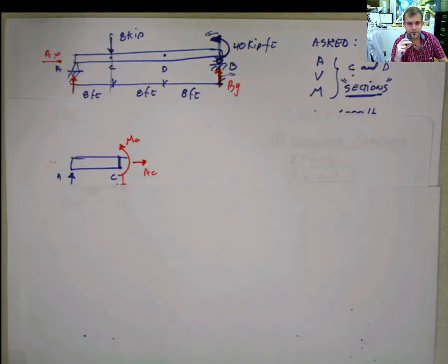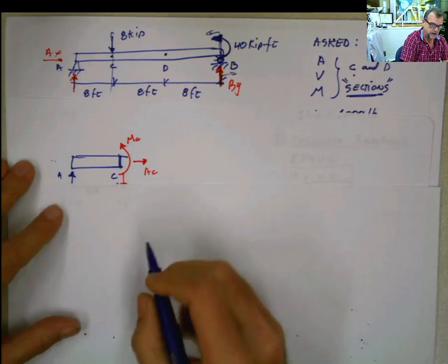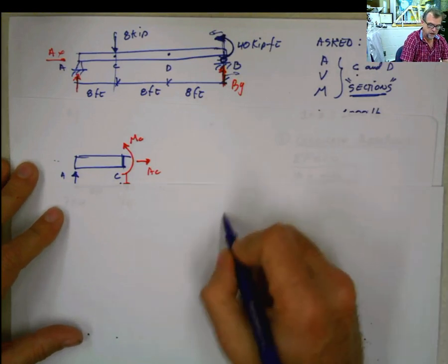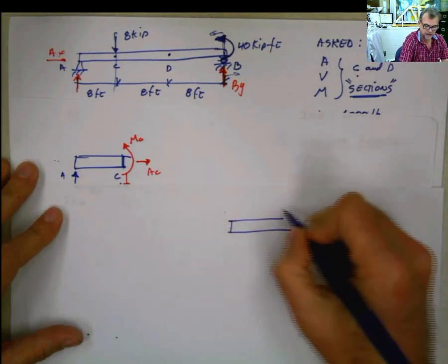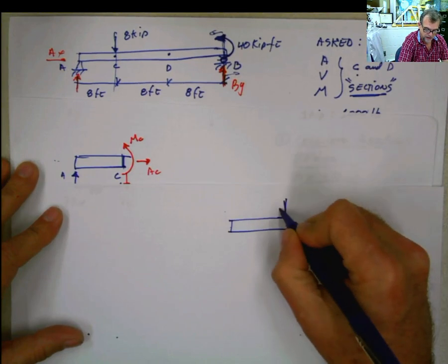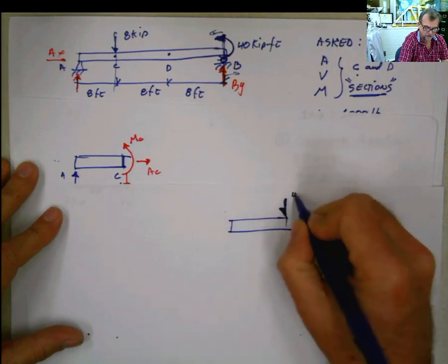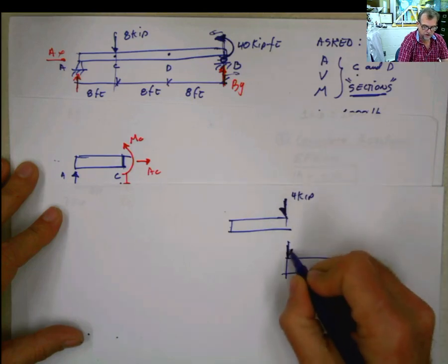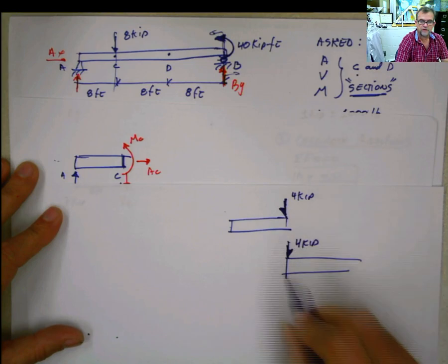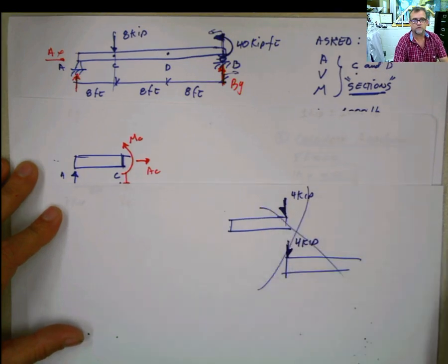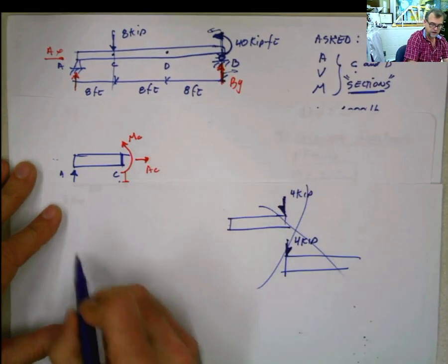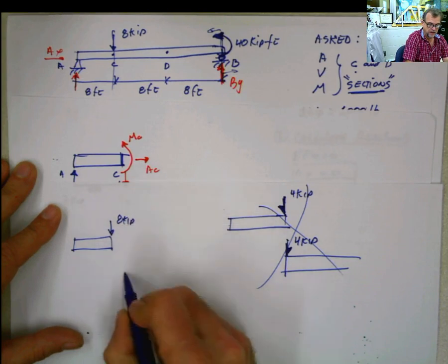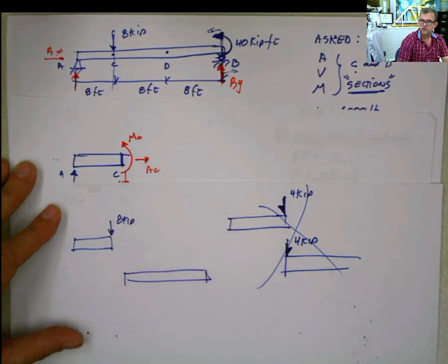Yes, you're right. And there are people that say, you know something, I'm gonna use the Solomon rule here. I'm gonna cut it. So if that force is 8, I'm gonna put half of the force in this side, 4 kip, and in the other side I'm gonna put the other half of the force, 4 kip. Well, if this is your theory, you are the one that did it wrong. But if you include it and you say, I'm going to put the force of 8 kip there, and in this side I'm not gonna put the force, that is correct.